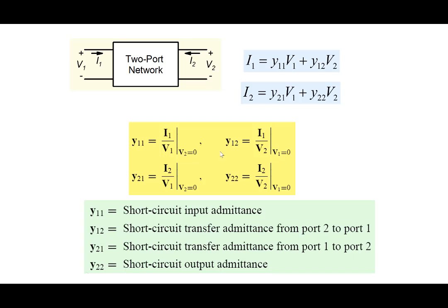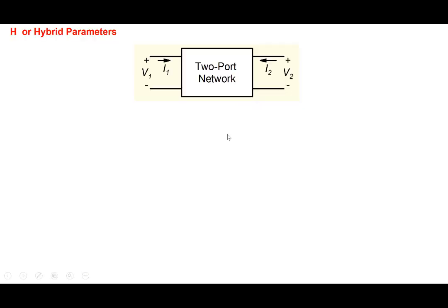All right, so Y parameter is another representation of the two-port network. And now I'm sure you can think of other ways of doing it also. For example, we could choose I1 as an independent variable on this side and V2 as an independent variable, and thereby express V1 in terms of I1 and V2, and I2 in terms of I1 and V2 here.